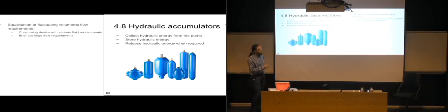And also if you have brief but very large fluid requirements, so that if you have a gigantic piston that's going to be operated somewhere in your system, then it could be nice to have an accumulator that assists in delivering fluid to this particular piston, because it might be that your pump can't really handle the piston and the rest of the system all on its own. So that when this large piston is in operation and the rest of the system also is supposed to function, then you need an accumulator to help run the piston.